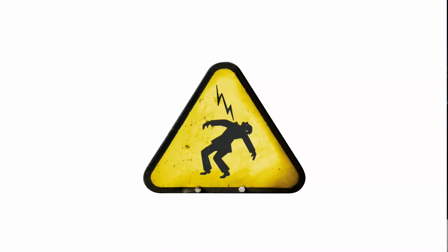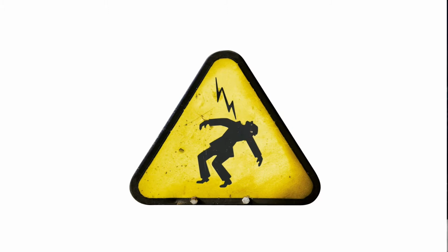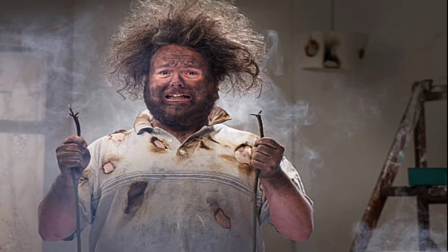Varying levels of amperage cause varying responses from the body. At a range of 1 milliamp, that's 0.001 amp, to 5 milliamps, a typical person will experience an involuntary action, such as arms or legs moving uncontrollably. This can be exceedingly dangerous, however, because oftentimes the subject is unable to release themselves from the energized object. This is known as the let go threshold, and it's around 20 milliamps or 0.02 amps.